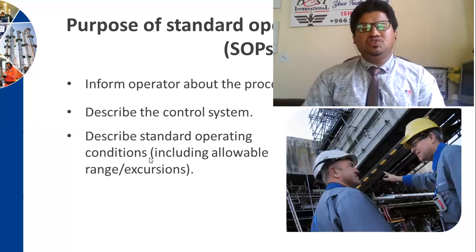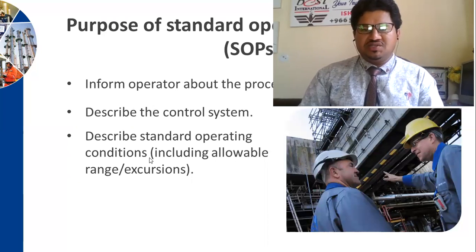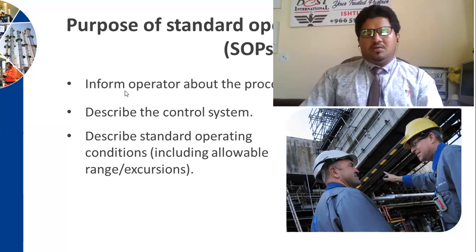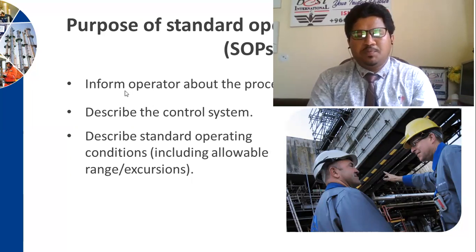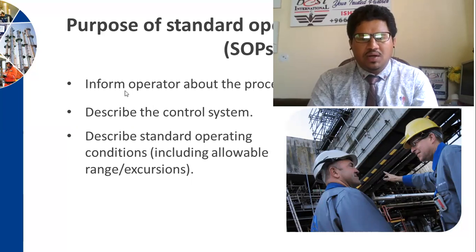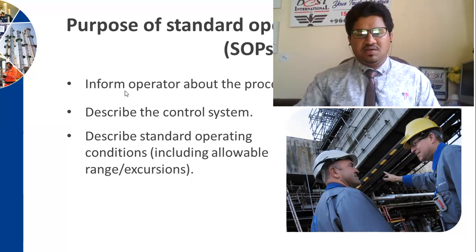Now, what is the purpose of standard operating procedures, SOPs? The biggest purpose is that it will help inform the operator about the process safety hazards. It will also describe the control system and describe standard operating conditions, including allowable ranges and deviations.